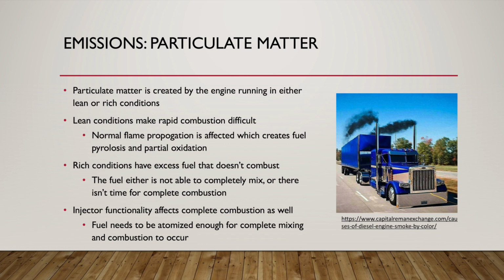And so this fuel is either not able to completely mix because there's too much of it and there's not enough time for it all to mix to complete combustion. And so what happens here is we have the engine not running perfectly where it should. And so we're going to create more particulate matter emissions. And so another thing that can affect that is injector functionality, because the fuel needs to be atomized enough so that it can mix and combustion occur.